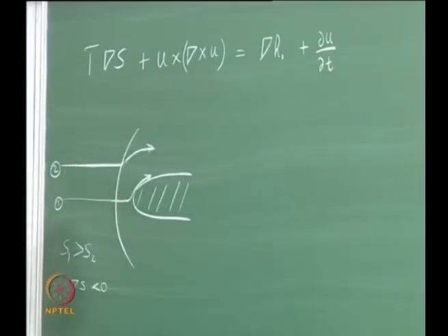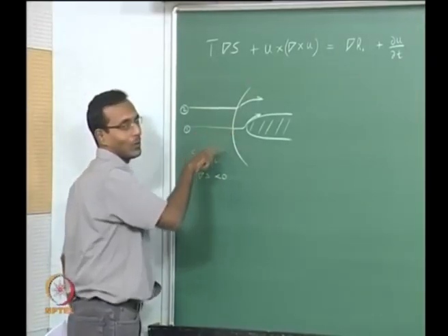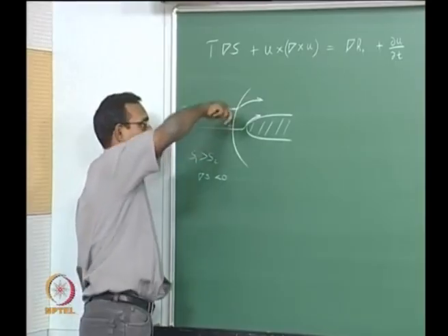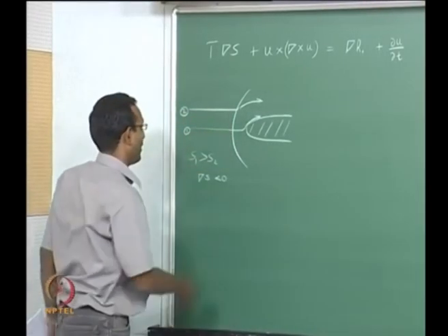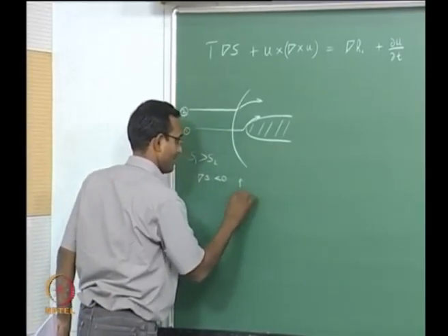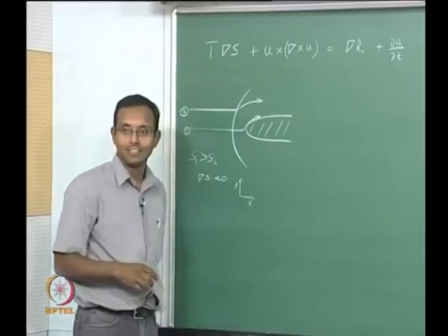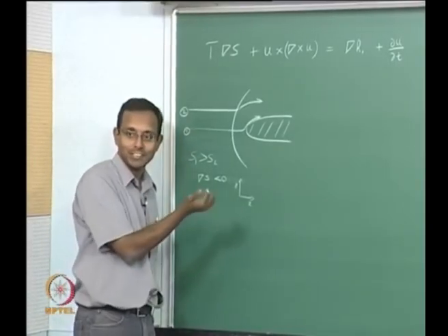Okay. What is the kind of vorticity I am developing? I have to match all these together. That is all I am thinking. What is the kind of vorticity I am developing? This is higher velocity and is going there. This is very, very low velocity. Overall, I am developing vorticity like this into the board. Okay. While my x and y coordinates are like this, right? X, y is like this. So I am developing, z will be out like this, right-handed coordinate system.